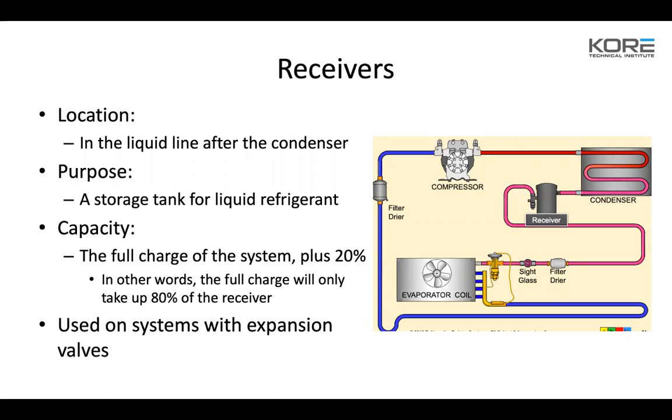So when we're snap torching those receivers, should we see them more full or more empty this time of year? Full. So it depends, that's kind of a trick question. If you're dealing with an indoor unit, yeah, they're going to want to stack there. If you're dealing with an outside unit where the condensing unit is outside, like on a remote system or a walk-in cooler, you're actually going to be more empty because the refrigerant is going to be where? In the condenser. Yep, it's going to be stacking in those condensers. So it's a good point of discussion today.